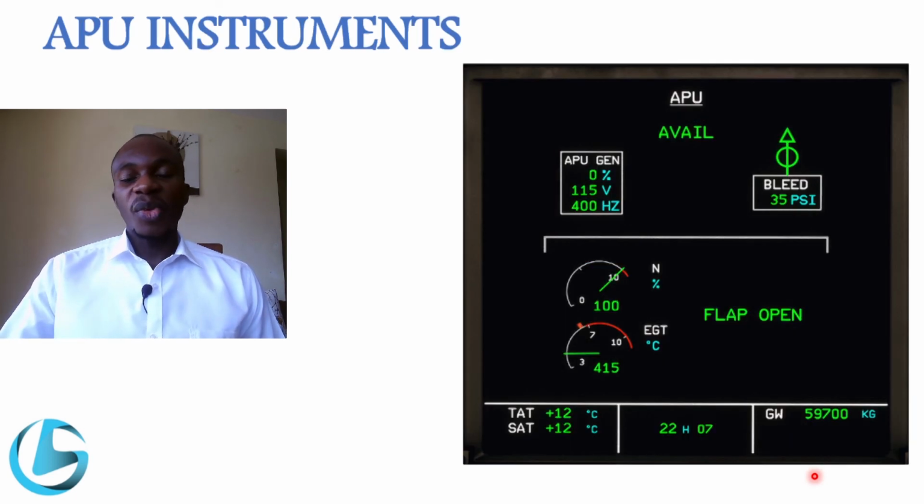This is the APU indication. You remember we've seen two analog indications for the APU where an exhaust gas temperature is indicated, and then we also saw the RPM. Now for an aircraft that has an ECAM, on modern aircraft, we have the RPM indicated here in percentage and the exhaust gas temperature in degrees centigrade.